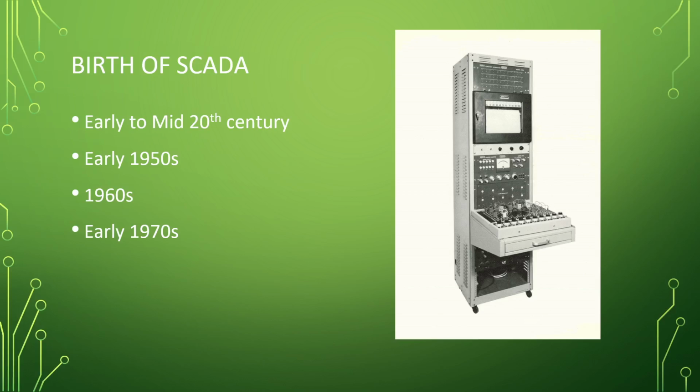You literally had cards that had a whole bunch of different holes, and you would punch out the holes that you wanted. That would do certain things. And then you would feed this into a computer, and there was a whole bunch of limit switches that hang down, and you'd feed your punch card in, and certain limit switches would be extended, the other ones wouldn't because they'd be hitting the card. And that would tell the process, extend the cylinder, and then it would advance that thing forward one notch. And then it would go, do this. So they actually would put just holes in a card, and that'd be their programming.